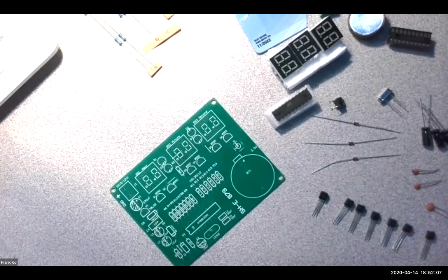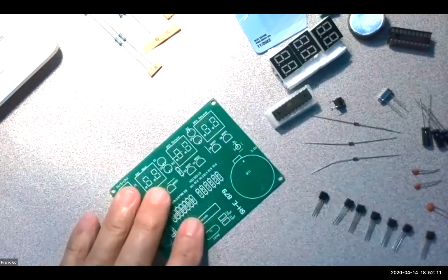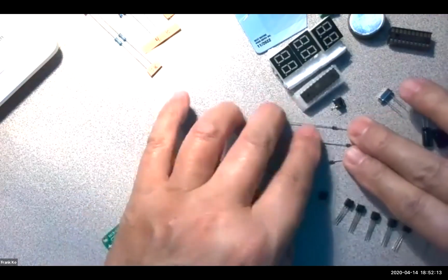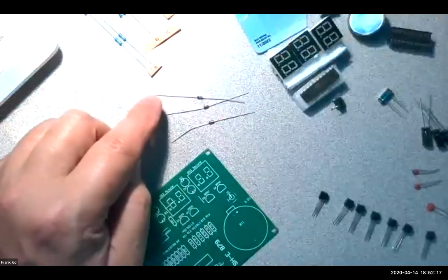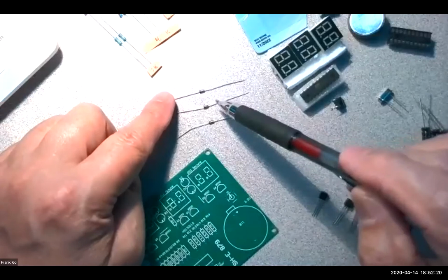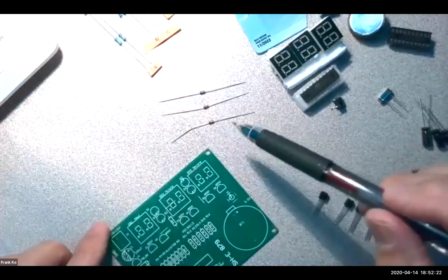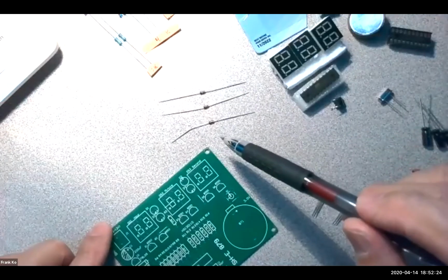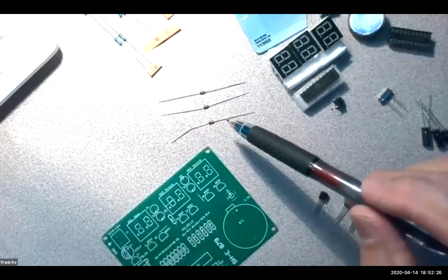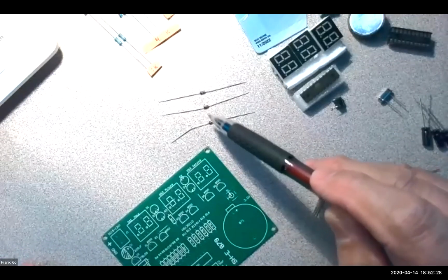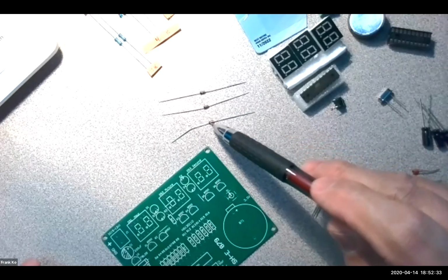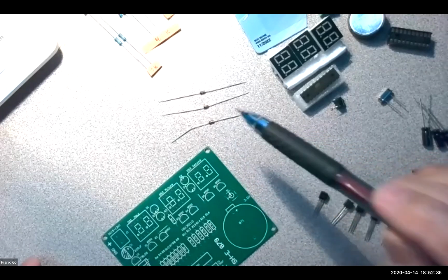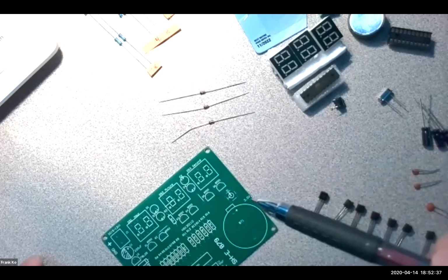Then you happen to have some diodes, these diodes, very small. They are, yes, it looks like glass, it is glass. These are glass encapsulated 1N4148 diodes. And these diodes, you can tell, are polarized. There's a black band that's characteristic on one side of these components. This is a polarized component. You wire this in backwards, this circuit will not work.